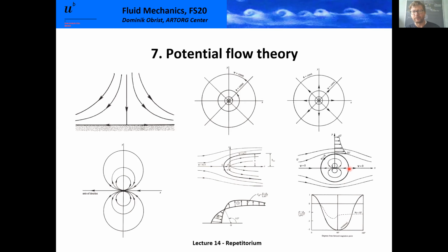In a mathematical sense, it's a correct result for potential flow theory. In practice, we know that this result is completely useless. This tells us that potential flow theory is not good to compute drag forces. It's very good to compute streamlines and maybe pressure forces on the upstream side, but on the downstream side, it actually does a very bad job. We only learned in lecture number 9 or lecture number 10, I believe, on aerodynamics, that we obtain a wake here, we get flow separation here, and we have asymmetric pressure conditions on the upstream and downstream side. That's where the drag is coming from. Plus, of course, the friction drag from the boundary layers, which is also neglected.